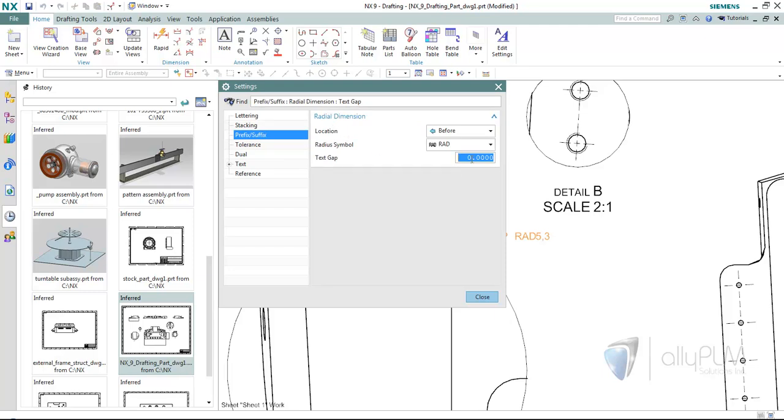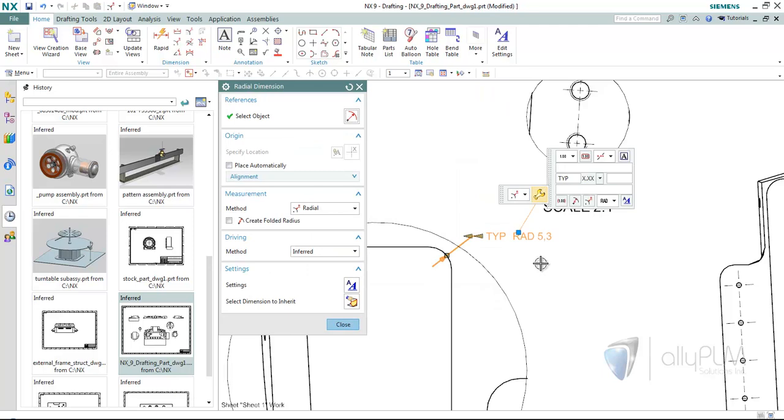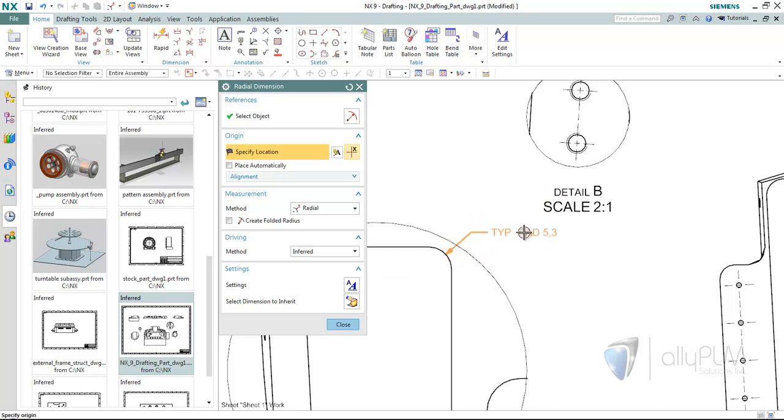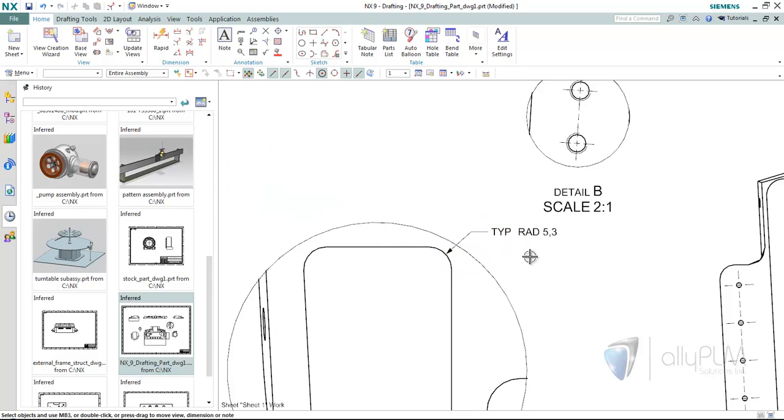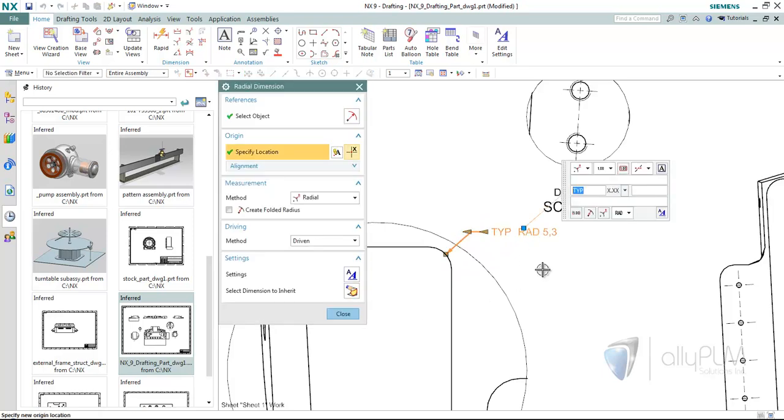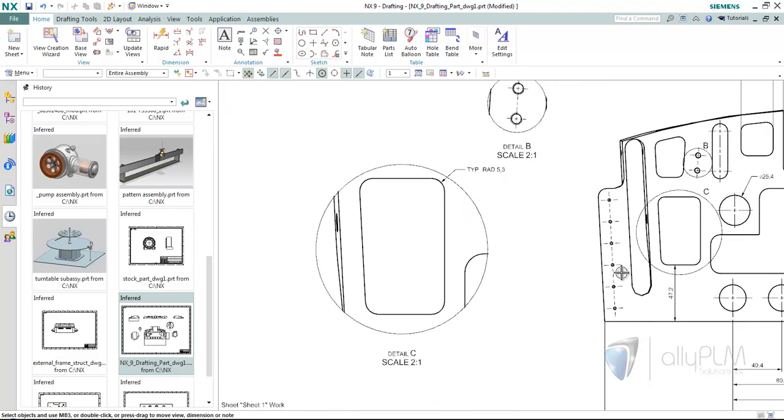So right there's the value I need to change, 0.5, which is going to give me a little spacing in between there. And once again, I can adjust the stub length. If I want to go down this hotspot, I can make the arrow out. And I never placed it, but if I turn off the wrench, now I can go ahead and place it. Once again, if I needed to edit, I can just double click it and go right back into my hotspot once it's created.